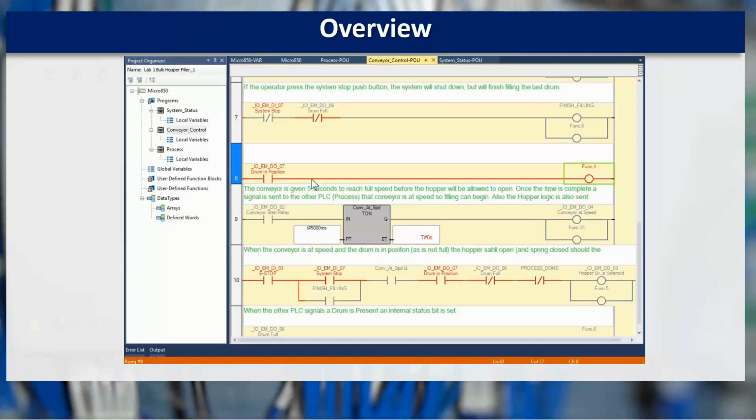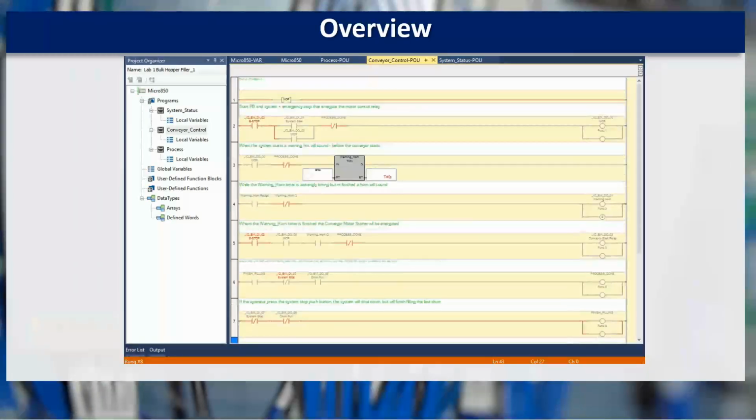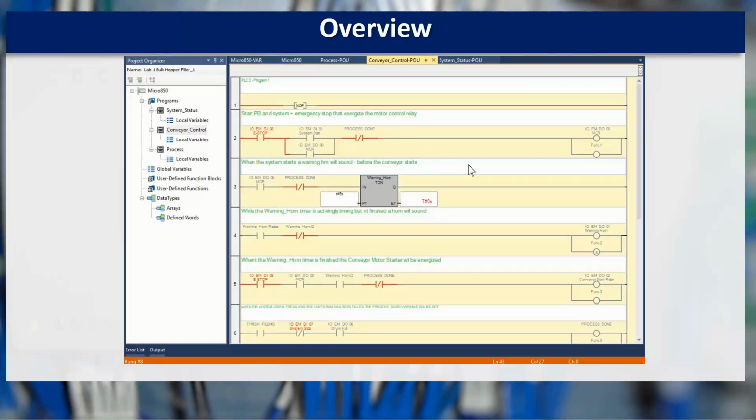In the program itself, quite a few were on the right track. Some of the simpler processes were taken care of right away. The tricky part was the last part, which I'll get to. So I've got a simple rung here, and my function 1 means the MCR is turned on. In order for me to do that, I simply have to toggle my start button. The MCR seals in, and my function 1 is also on.